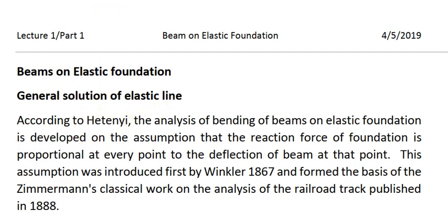According to Hetényi, the analysis of bending beams on elastic foundation is developed on the assumption that the reaction force of foundation is proportional at every point to the deflection of beam at that point. This assumption was introduced first by Winkler in 1867 and formed the basis of the Zimmermann's classical work on the analysis of railroad track, published in 1888.